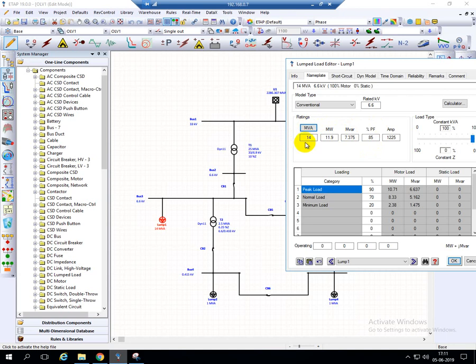Depending on this power factor, both will change. If the capacity is 14 MVA and you want the megawatts to also be 14, then the power factor should be 100%. Practically we can't reach a power factor of 100%, so industries maintain a power factor near 0.9 to 0.95.